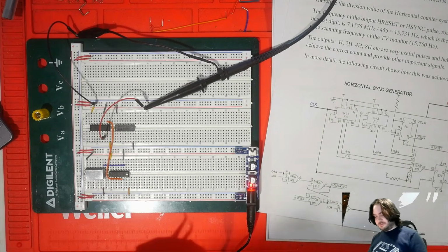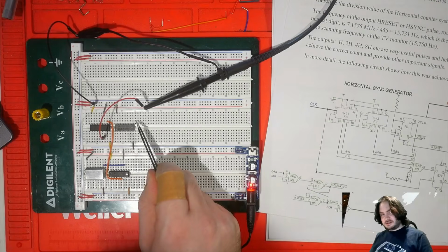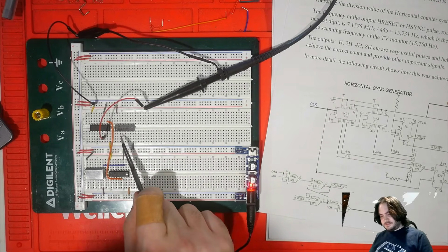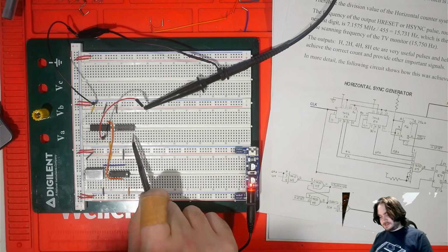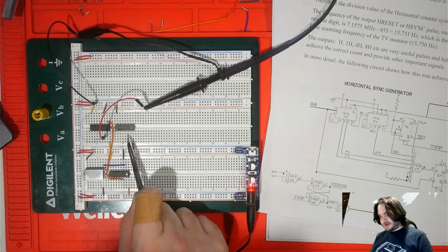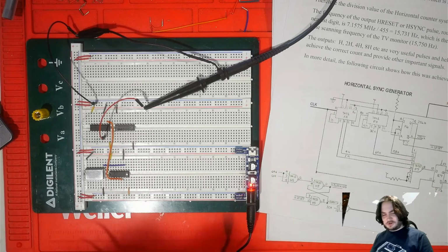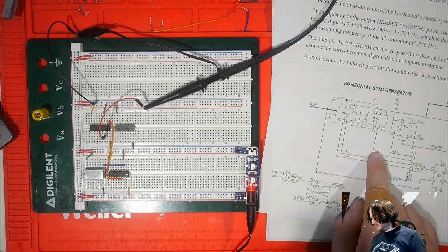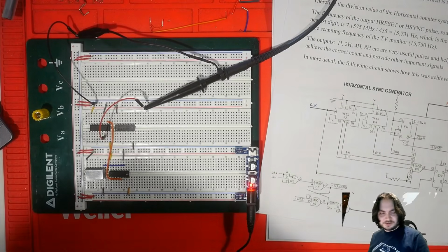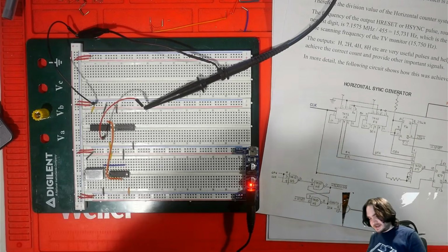On here, the output is going to be this last pin. Everything on this side is an input. 1, 2, 3, 4. Well, not this side, that's ground, but 1, 2, 3, 4, 5, 6, and then 7, 8 are over here. We're actually only combining 2, 3, 4, 5 signals, so 3 of them are actually just going to be tied high.